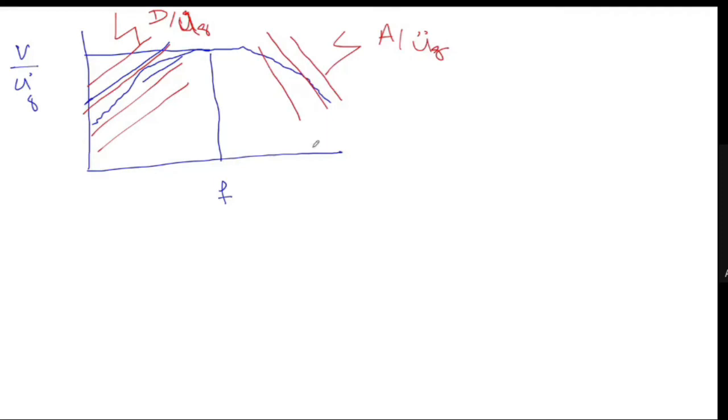Okay, so this plot had the advantage of providing you all three values just by knowing the frequency of vibration, the vibration period, or the cyclic frequency of the structure. And if you look at such a plot for a number of single degree of freedom systems, let me plot it here again. What Newmark did is that they developed this kind of spectrum for a number of accelerograms, and let me give you the detail of what they found. This is what they saw.